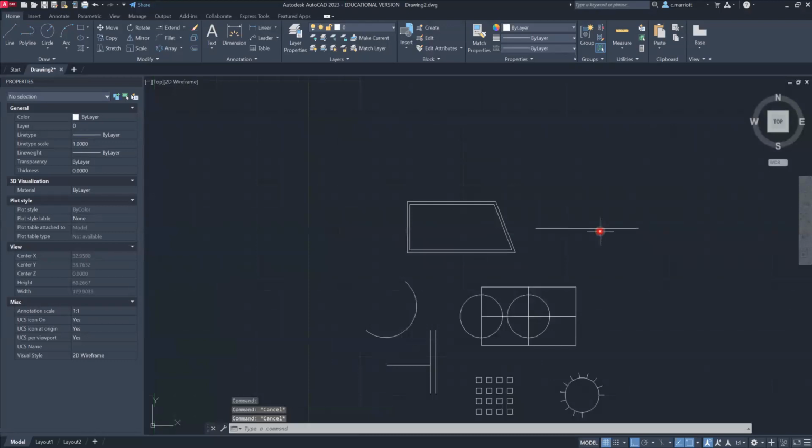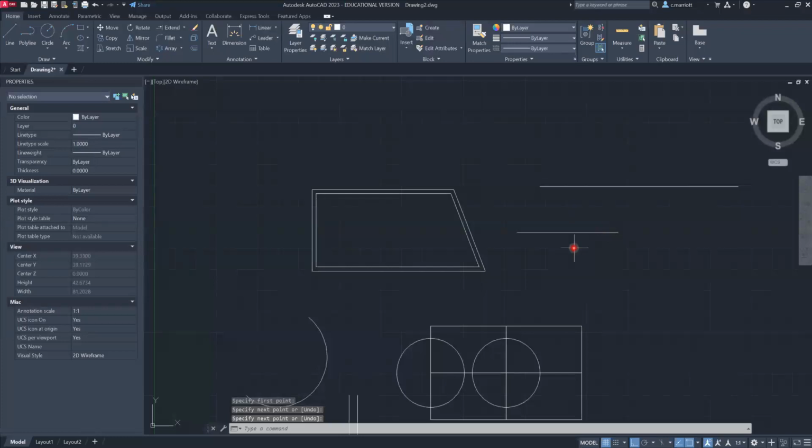Now I can also use this tool. So let's undo here. Let's say I have a line here and I want to make this one as long as that one. I can use the same tool. So let's go to Lengthen. Okay. Select object to measure. Press enter. I'm going to click on these two endpoints, and then it's asking me to select an object to change. And I'm going to click on that same line. So now they should be exactly the same. Distance, 24.1007, 24.1. So it's kind of like a way of matching a length.